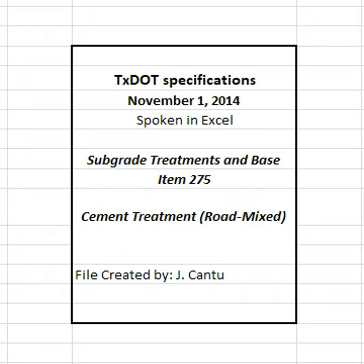3.3 Dry cement distribution equipment. Provide equipment to spread cement evenly across the area to be treated. Provide equipment with a rotary vane feeder when shown on the plans. 3.4 Pulverization equipment. Provide pulverization equipment that cuts and pulverizes material uniformly to the proper depth with cutters that will plane to a uniform surface over the entire width of the cut, provides a visible indication of the depth of cut at all times, and uniformly mixes the materials.